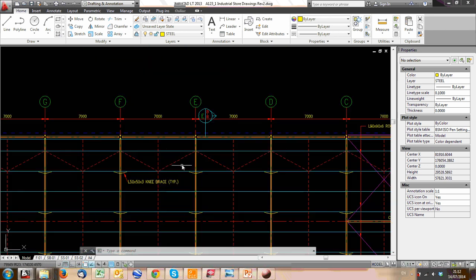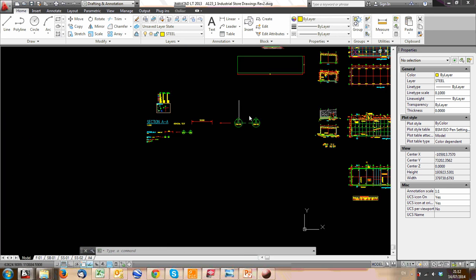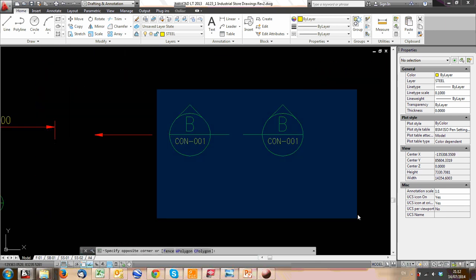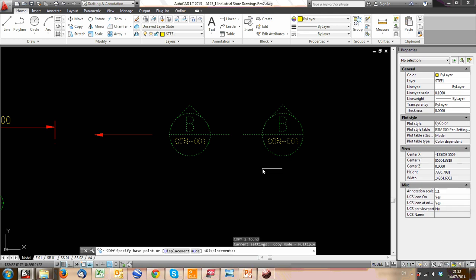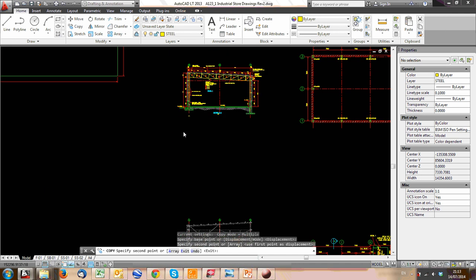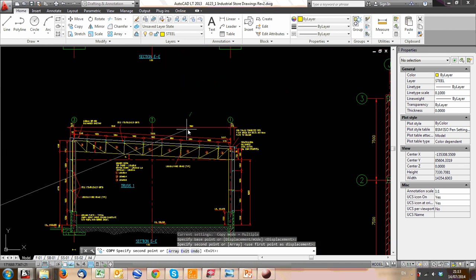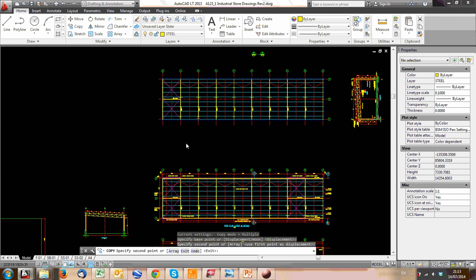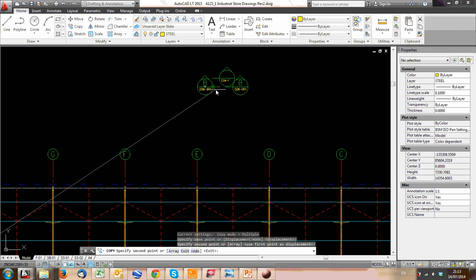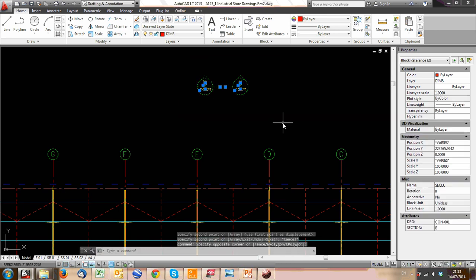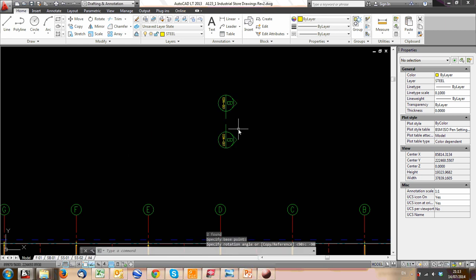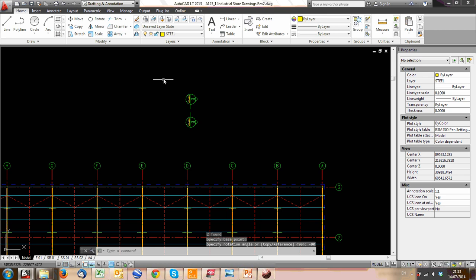Now we can start adding section marks to our drawing. Let's say I haven't got anything yet. I go here, this is a 1 in 100 drawing, so I can select that. Copy, enter, move it up here. Because we created that section earlier, section EE. So it's grid line 3 on the left, grid line 1 on the right. So it means we're looking from left to right. So let's rotate this, rotate. And it's 90 degrees. So that is the way we are looking.